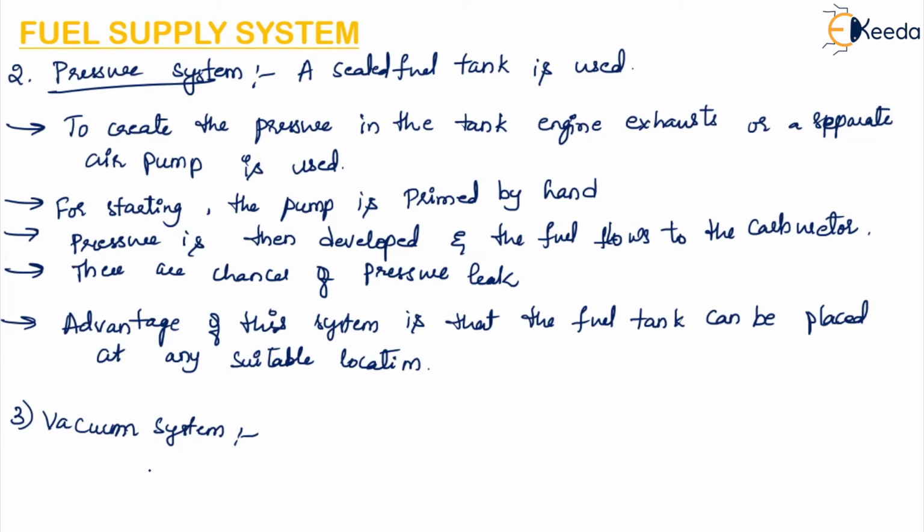This system is based on the simple fact that engine suction can be used for sucking fuel from the main tank to the auxiliary fuel tank, from where it flows by gravity to the carburetor float chamber.